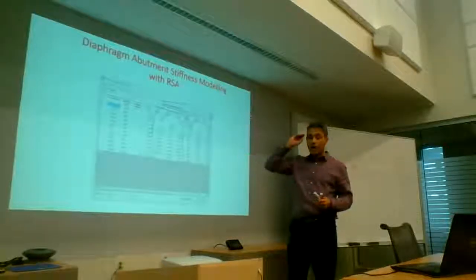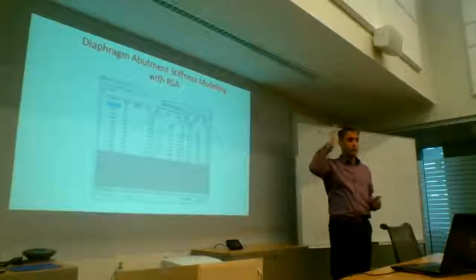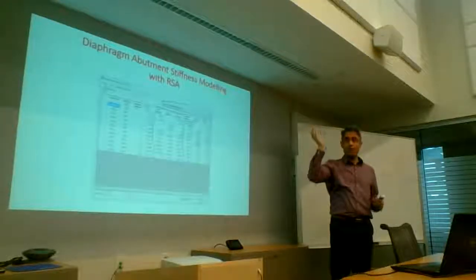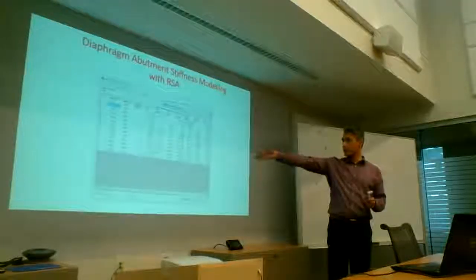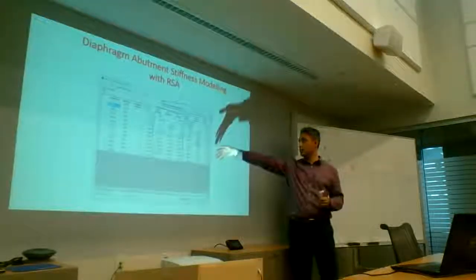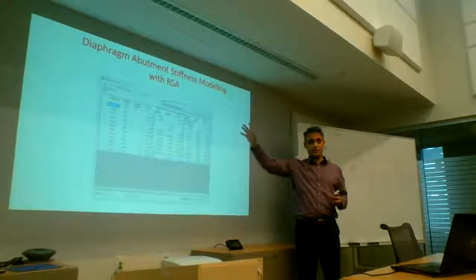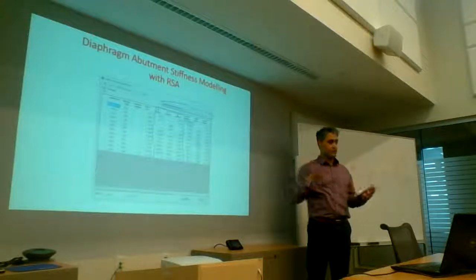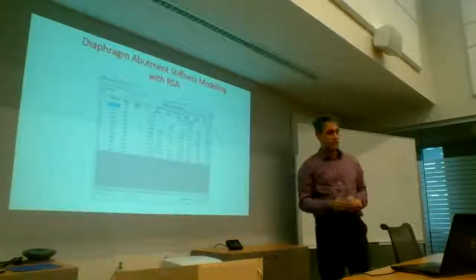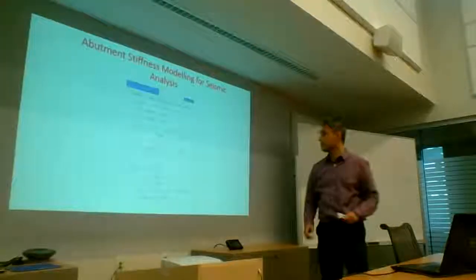So really, I have been involved with some complex bridges where we've had to run over 200 modes, 500 modes to capture that 90%. And then on a simple bridge, this is again telling you that this structure is really behaving in both directions as a single degree of freedom system. The first mode for each one of the directions, principal directions, captures the entire modal mass contribution.